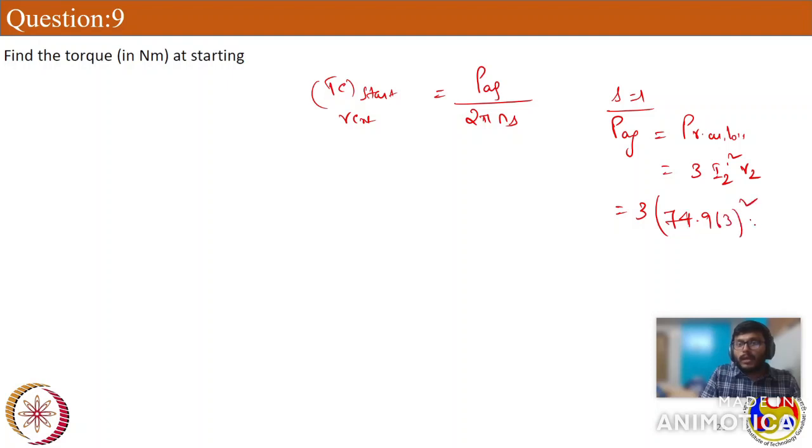74.963 squared into R2 is now R2 plus R external. That is the rotor circuit. So that is 0.25 plus 1. Now can someone tell me what the answer is here? 74.963 squared multiplied by 1.25. It's 21 point... okay, anyway, air gap power is 21072.942 watts.